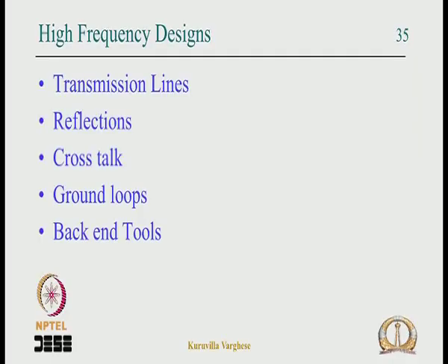What is the next issue in design? That is high frequency design. You know that at high frequency the tracks or the lines or the wires on a PCB or a chip can act like transmission lines. So there could be reflections. Unless we take care, maybe your logic is correct, the timing is correct, everything else is taken care of, but because of the high frequency the wires can act like transmission lines. If there is an impedance matching problem, there can be reflections which can corrupt the signals. So this has to be taken care of in high frequency design.